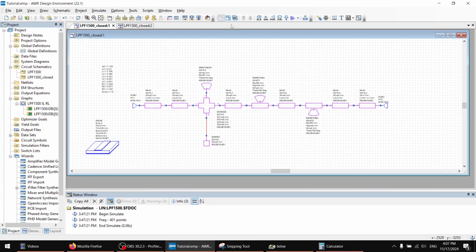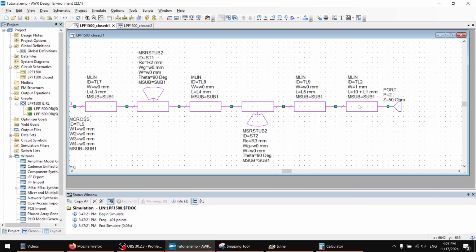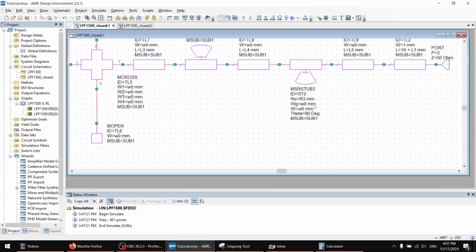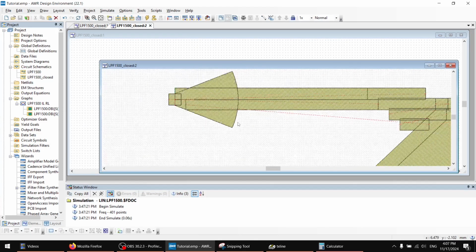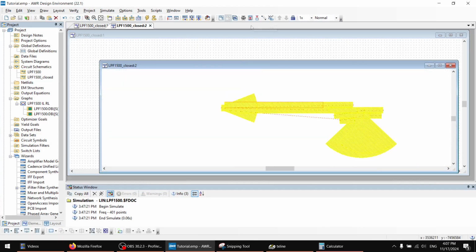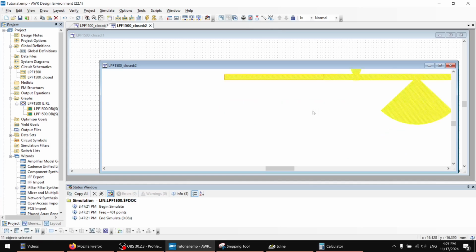So it looks like we are practically done here. Everything seems to be set up. So let's see how our layout looks, because sometimes we can get some surprises with that. So press this layout button over here. Now I will press Ctrl and A, so select all, and then we'll have snap together.